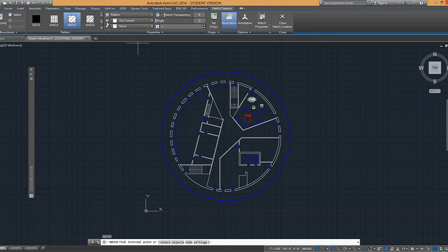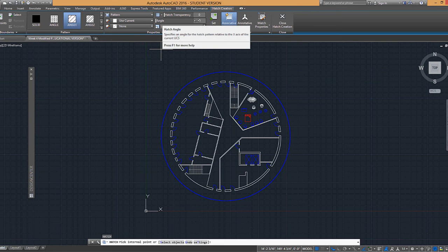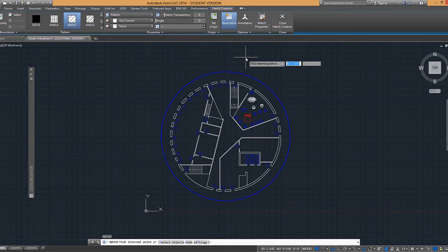This also has options for transparencies. We're not going to work with transparencies. You can see in the handouts that there are some issues with it, so they're not really used all that often. They have their issues, etc. We can change the angle of our hatch, and we can also change the scale of it, and that's going to be important when we start to work with hatches.